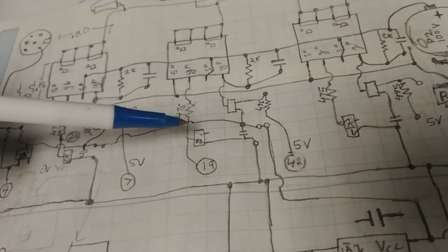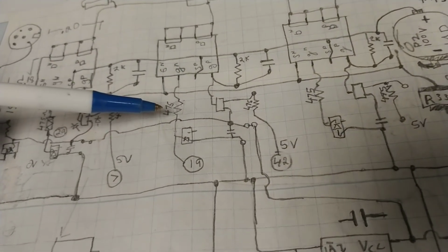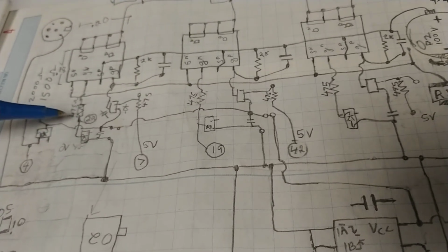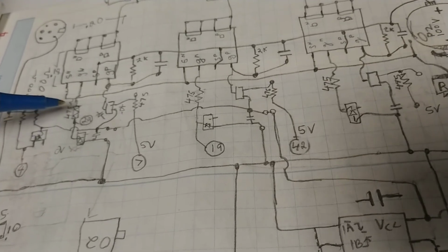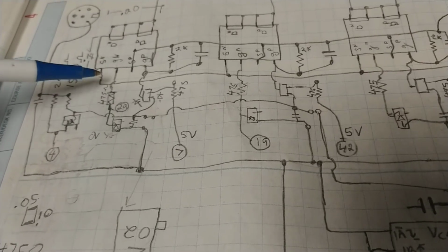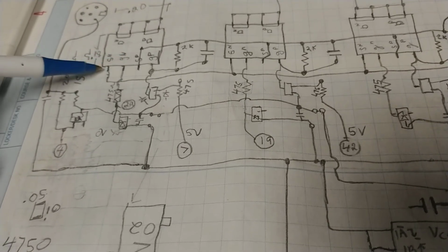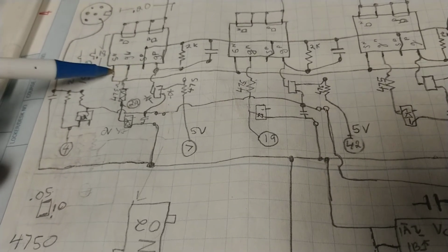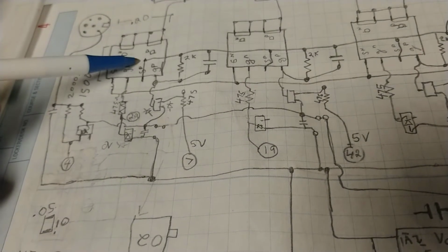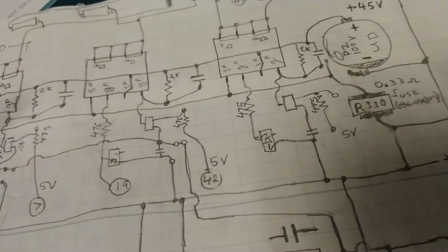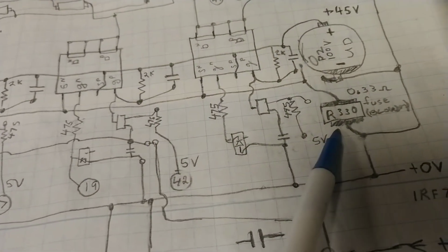However, because we had some nice identical circuits, I could get the number of the resistance. The 475 burnt resistor had increased its ohms, which is good. It increased instead of decreased, to 2,000 ohms or so. Also, the resistance between the gate and the source was 0 ohms. So this little fella is blown. Got to replace that, and that. And hopefully I'll get me a working hot plate.